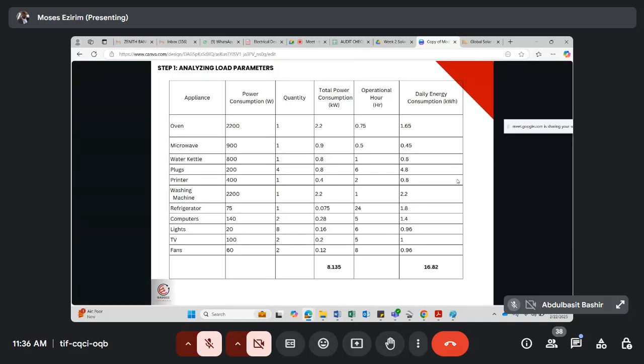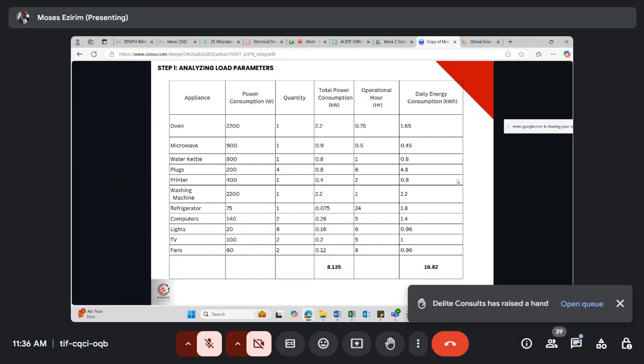Maybe it's just a small office, they operate during the day, and their load is not that much, maybe just 2 ACs. And they don't want to pay much money. I can decide to do a DC coupled system for them. But if they operate at night, and you want to carry them all through, definitely AC coupled is what you should recommend.